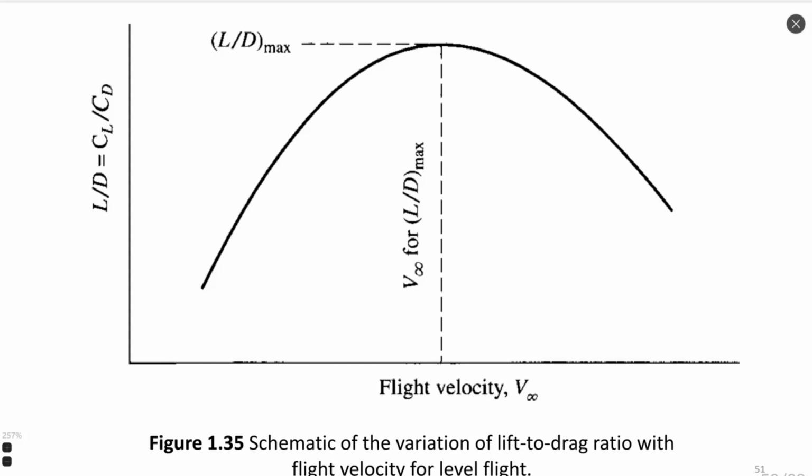It's not important if you have just high lift but you have very high drag as well. And vice versa, it's not important to reduce just drag, to reduce just losses. You also need this airplane to carry some weight over some distance. So the correct criterion from an aerodynamic point of view is the ratio between lift and drag. It's also the ratio between weight and thrust of your airplane, which is the same. Lift to drag is the same as weight to thrust for constant velocity and constant altitude flights.